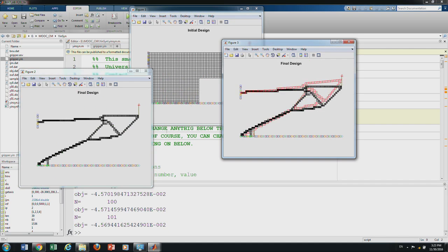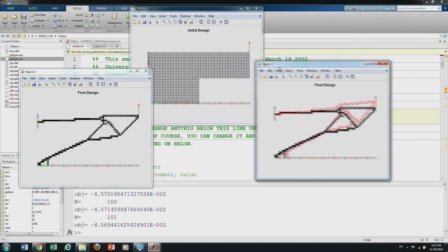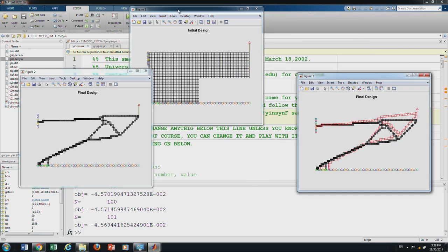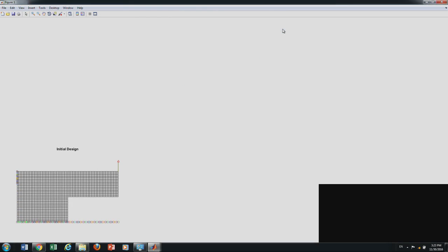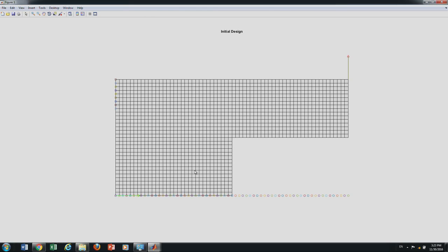Now it is giving the solution. So, you can see what we have put here. So, let us look at the specification. We have taken a domain where there is a hole already, meaning that it is an L-shaped domain. We have taken a big rectangle and subtracted a smaller rectangle. Our boundary conditions are that this edge here is fixed, meaning that both x and y degrees of freedom are fixed. It is a 2D implementation, not a 3D, everything is planar.